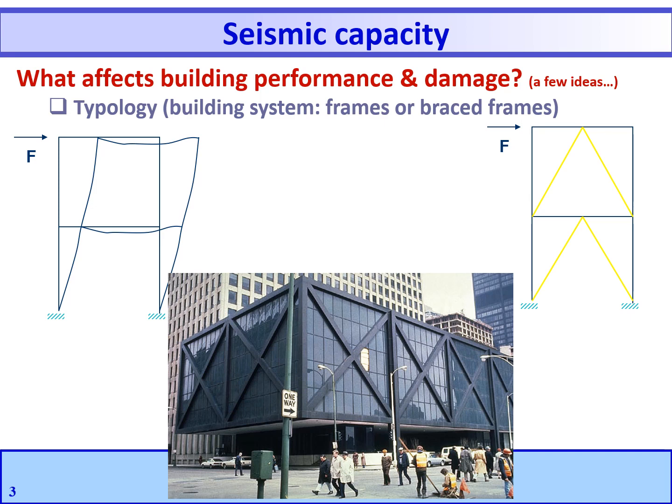Steel structures are considered the most seismic resistant, allowing smaller member sizes compared to reinforced concrete. But now, after the experience of the Northridge earthquake in Southern California, steel structures have progressed from a simple steel frame braced laterally by unreinforced masonry, for example, to complete moment frames with full lateral load resistance.